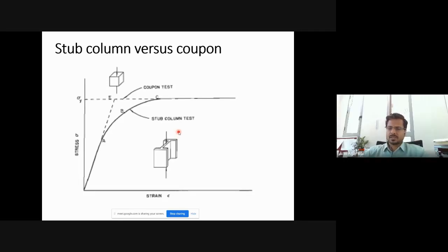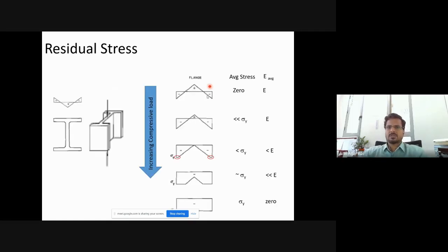Good, fine. That's the correct answer. So basically, you already have some stresses. To start with, the net total stress in the cross section is 0. However, that is the average stress. If you look at individual locations, you will see that they have some stresses, but they are distributed in such a way that the net stress, or average stress, is 0.